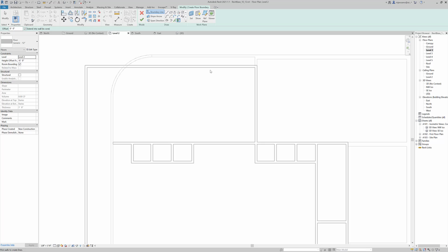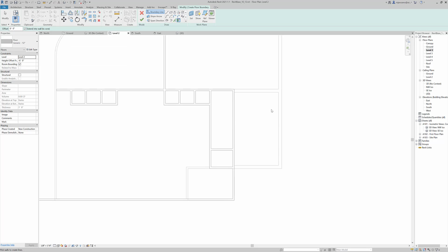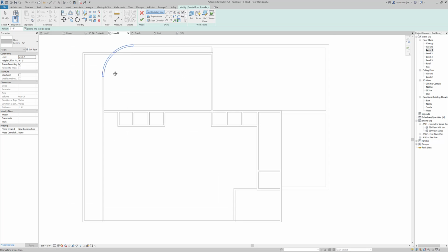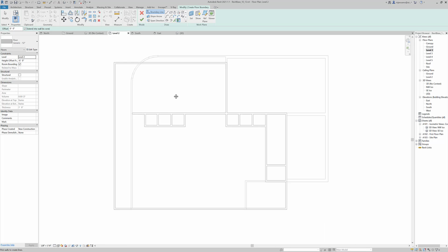What I mean by that is where you want your floor to end. So the foundation will actually probably continue past, and you'll actually have probably an edge beam, and we'll get to that when we talk about foundations in this class. Or we'll have a spread footing, you know, if you're in an earthquake zone or a place with kind of bad soil, you might have some piers.